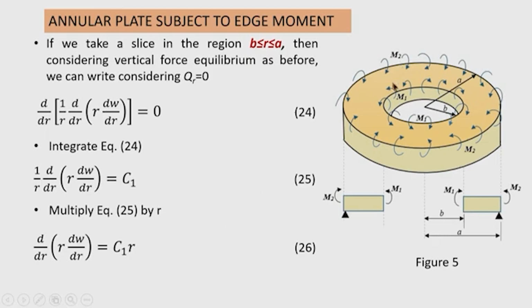So, for these columns arranged in the circumference of the circle, it will be convenient to adopt an annular raft foundation accommodating all the columns. So, this type of problem finds application in practice, and plate theory for finding the stress resultants can be used.